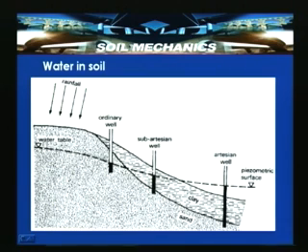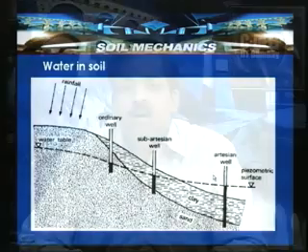So, what we have seen in this slide are the ordinary well, subartesian well and artesian well. Many times when we are constructing structures on a soil stratum under artesian conditions, or carrying out excavations under artesian conditions, one has to ensure the stability. If the stability is not ensured, then effective stress tends to become 0, and there is a chance of failure, caving in or collapse.